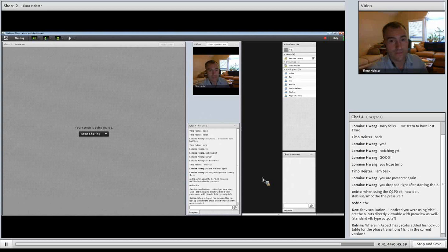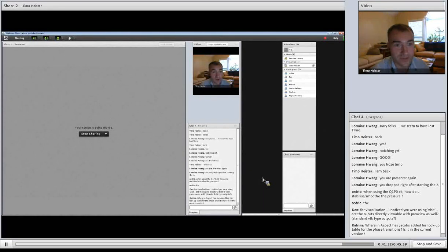Dan first. He wants to know if I can use something else than Visit. Yes. So I'm actually using ParaView normally, but inside the virtual machine I couldn't get it to work, so I was using Visit. The default is standard VTK output, and you can use Visit and ParaView, also in parallel if you have really big solutions. You can also use HDF5 output that can also be read by ParaView. There are many other file formats supported inside deal.II, so one has to see what works. But VTK output works with Visit and ParaView.